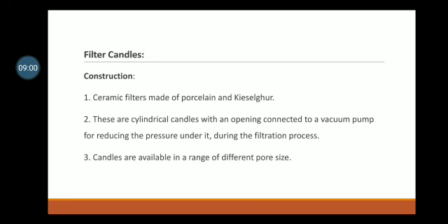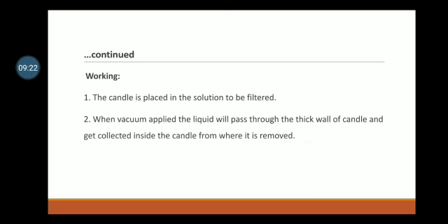Filter candles. Construction: ceramic filters made up of porcelain and kieselguhr. These are cylindrical candles with an opening connected to a vacuum pump for reducing the pressure under it during the filtration process. Candles are available in a range of different pore sizes.